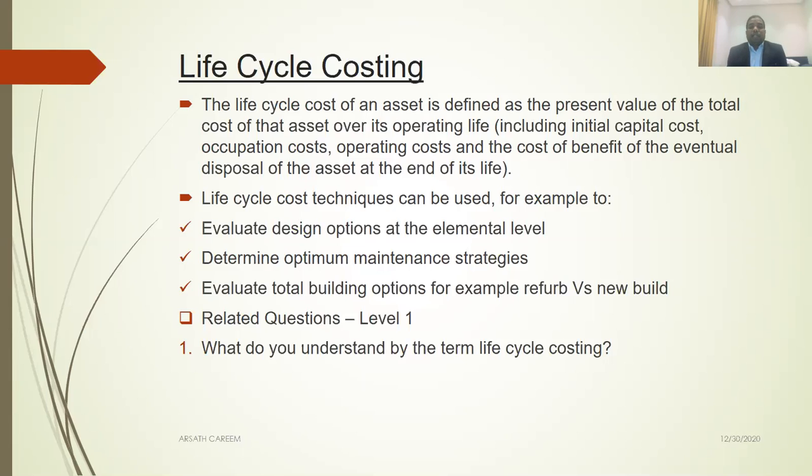The life cycle cost technique can be used, for example, to evaluate design options at the elemental level, also to determine optimum maintenance strategies, and to evaluate total building options, for example, refurbishment or new build. So based on the life cycle costing exercise, as a quantity surveyor, sometimes you have to do this.